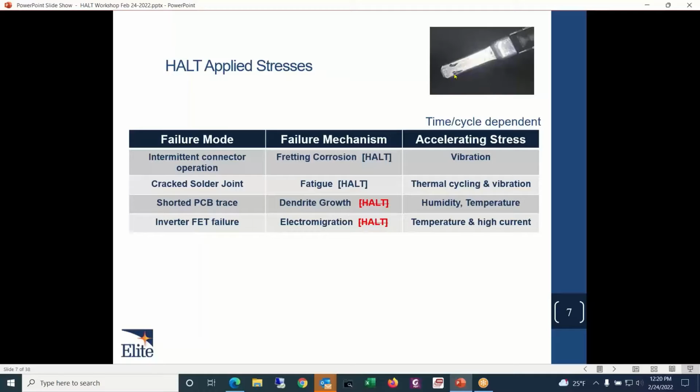marking on the connector interface here. And it generally is a sign, often a fretting corrosion issue, right? Fretting corrosion is created from micro displacements that occur when the male part of the connector interfaces with the female part. And with millions and millions of cycles back and forth, you start wearing away that coating, and you create a little bit of an oxide on there.